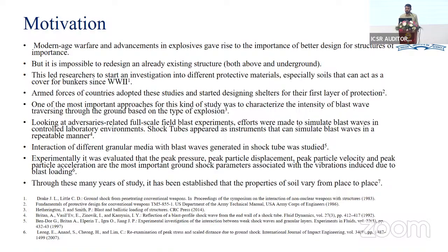do repeatable blast experiments. Experimentally, with the blast studies of the granular media, it was found out that the peak particle velocity, peak particle acceleration, peak pressure, and peak particle displacements are some of the most important things which can depict the behavior of a granular media towards blast loading.